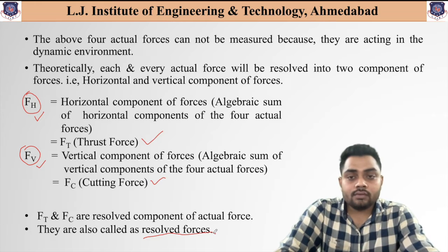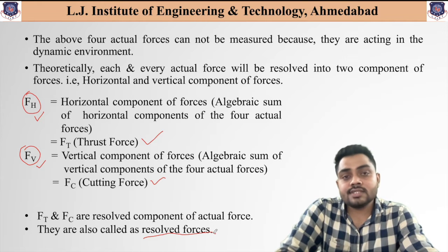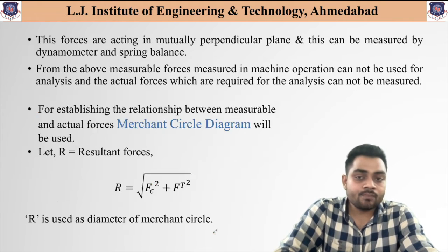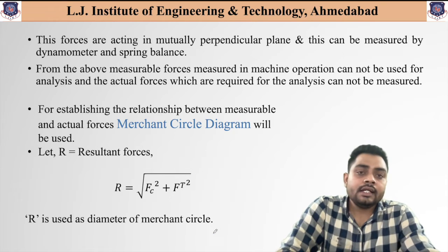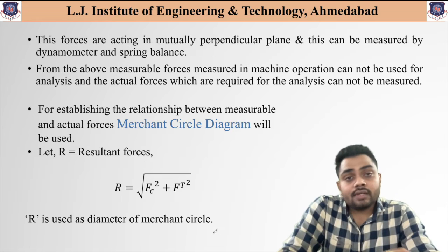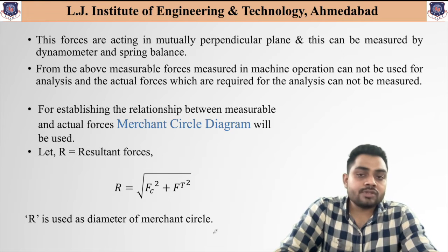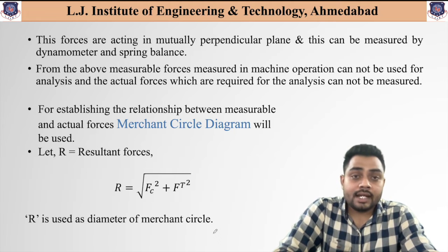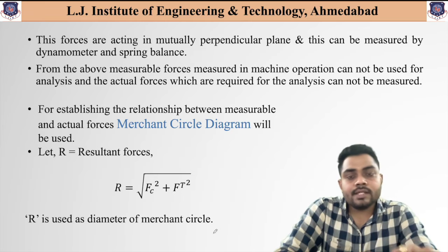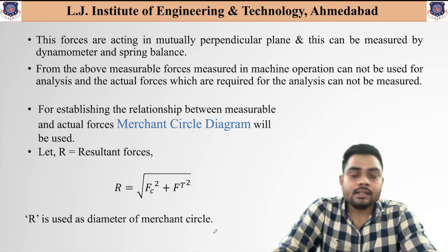I hope you now have clarity about which types of forces act during machining operations. All these forces act during the actual working condition, and they are not possible to measure. These forces act in mutually perpendicular directions, and the resolved forces can be measured using a dynamometer and spring balance.